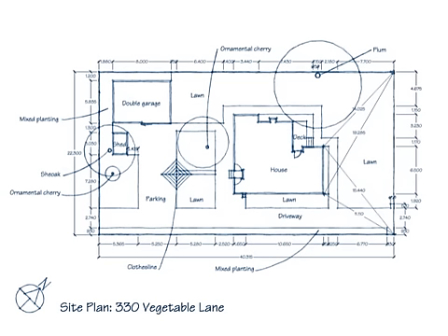The next step is to create an environmental plan, which records all of the environmental information about the site, such as dry spots, wet spots, sunny areas, shady areas, and changes in ground level. Other resources in this topic teach you about how to research and measure this environmental information, but this video shows you how to draw it up. To do this, we recommend that you place a sheet of tracing paper or butter paper over your site plan and tape both pieces of paper to your drawing surface. This will prevent them from moving while you draw your environmental plan.